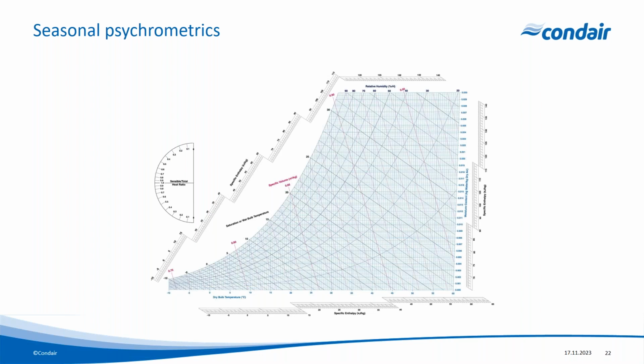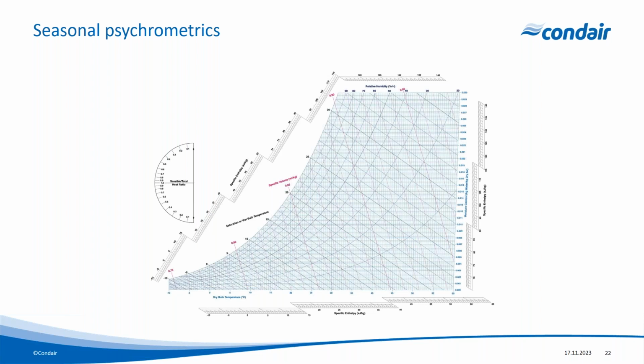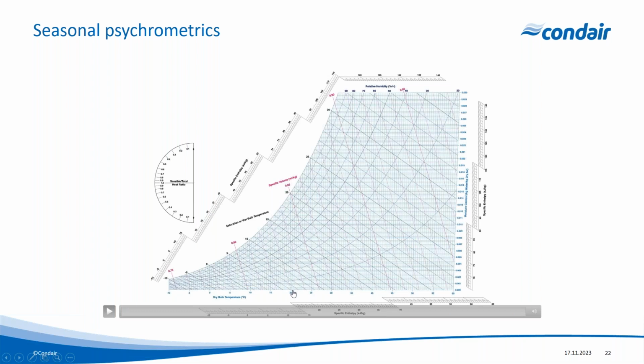We used an instrument called a whirling or a sling hygrometer, and it had two thermometer bulbs on it. One was a dry bulb, that gives you the dry bulb temperature, but one was a wetted bulb, a wet thermometer bulb. This glass thermometer bulb had a linen wick over it that was attached to a small reservoir of water. And as you slung this thing around in the air, if the air was 100% saturated, then no evaporation could take place and have a cooling effect on the thermometer bulb.